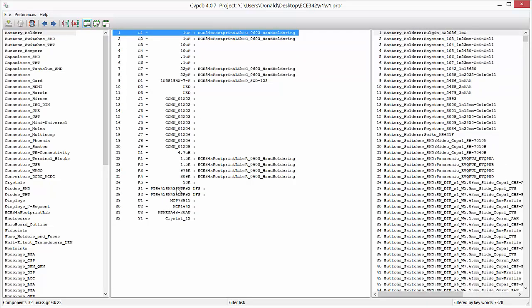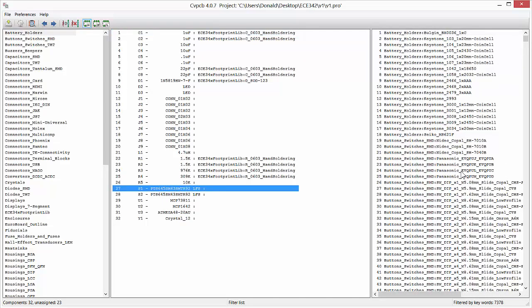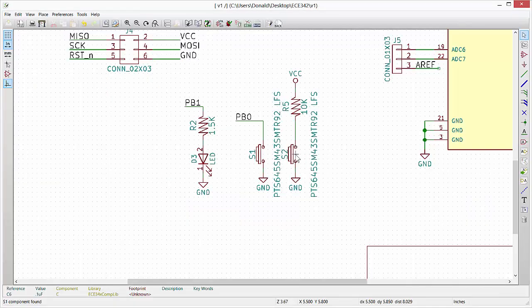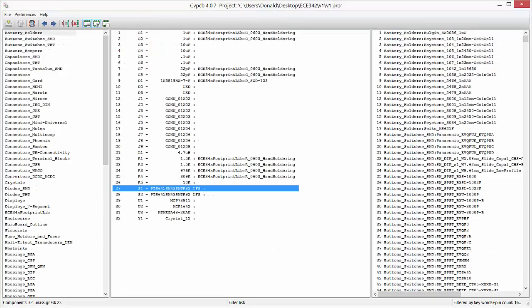All right. And we remember looking on our data sheet that this was a 6mm part. Currently it's filtering by nothing. We can choose to filter by other things, like we can filter by the number of pins, but this is going to be a little deceptive for us, possibly, because that switch that we have here in our schematic only seems to have 2 pins, but in reality we know that the part we want has 4 pins. So that may be an issue for us as well. But we're going to look for some options.